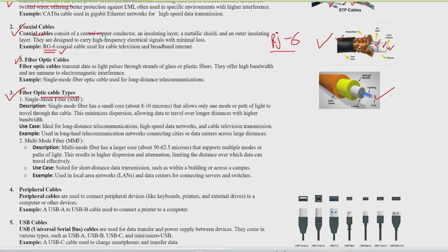They have made the glass, but inside the glass there is a way for light to go. So they have made a very strong structure. That is very thin, but inside the glass is where light is going. Okay. So to protect this core, so that light will not go outside, they have covered it with cladding. Some kind of material they have wrapped over the glass, so the light cannot go out. But still, that cladding is not enough. They have put some coating over there.